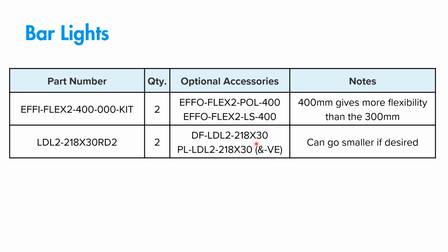So the polarizer, I've got this N-VE here, which means dash in the vertical direction. And this only comes in handy or is necessary if you have 4 bar lights around your application and you're using a polarizer. If you use the same polarizer on all 4 bar lights, then the polarizer on the lens will only ever be perpendicular with 2 of them at a time.